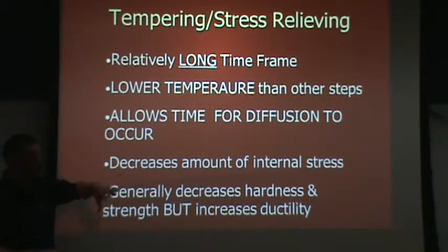Microstructurally, and I know we tried to do this in one of the labs, and the images didn't turn out as good as we had hoped, but when you're tempering something, you're starting with a fully martensitic structure, in the case of our example, which is BCT, right? We trapped all the carbon in this matrix. The carbon wants to get out, it can't get out, so we have something that's extremely hard.